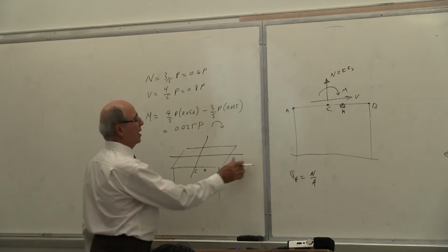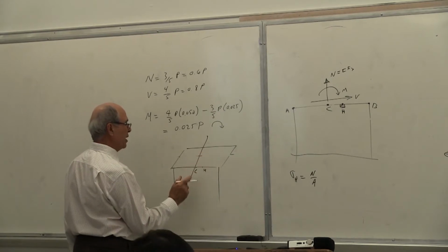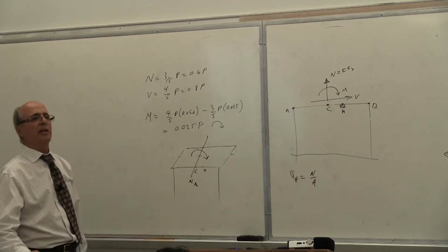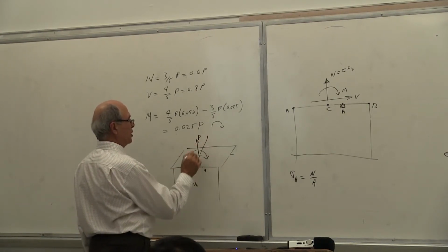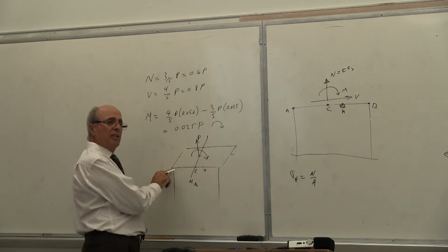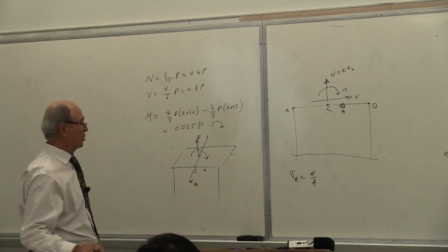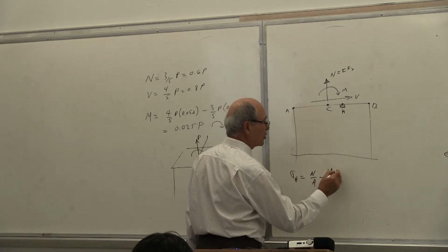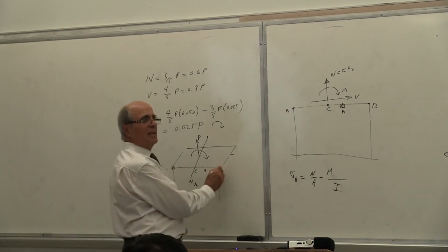Yes or no? Anyhow, this sort of thing, I would not buy it if you have gone through ME 218. This is your neutral axis because your moment is like that. Is that correct or not? What I'm saying is that you have this force, which gives you uniform stress, and this bending, where this side is in tension and this side should be in compression, yes or no? So sigma H is plus N over A minus M C. C is at A and at B.